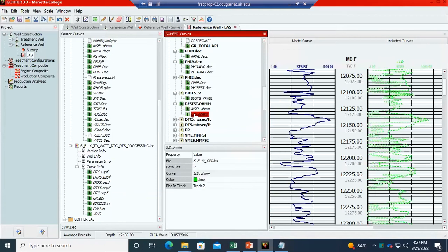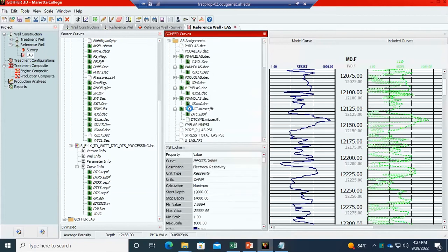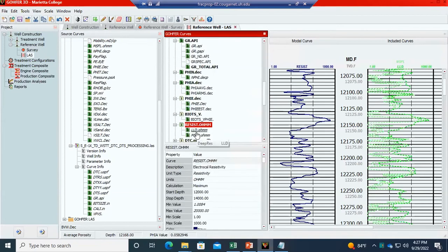The resistivity, you need to assign the right curve. If you have a box with multiple curves, simply drag the curve to the top. Once it reaches the top and the box is set to copy, it will take the value from the first curve.